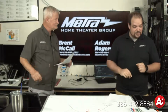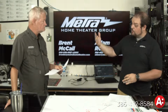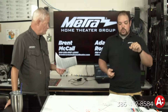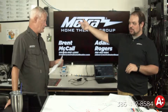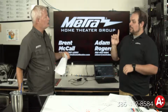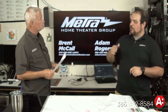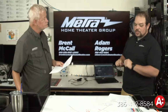Exactly. So the way it works is 802.3 AF, which is just standardized PoE, is alternative B, which we've been using since day one, and that's what all of our cameras here use. They supply power at the powered device, the actual camera, on the receiving side. So the PSE is the power supplying equipment, and the PD is the powered device. We're talking about the PD right now.